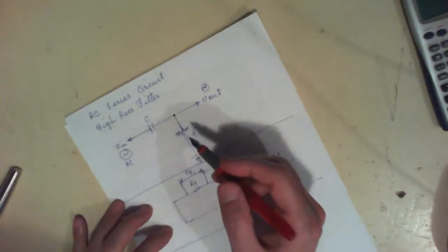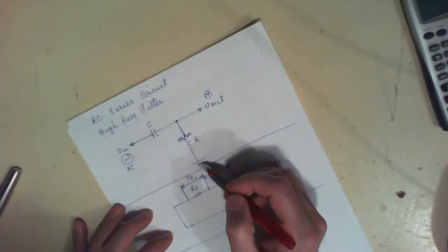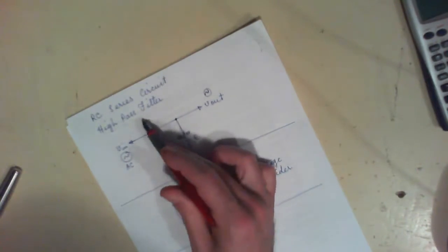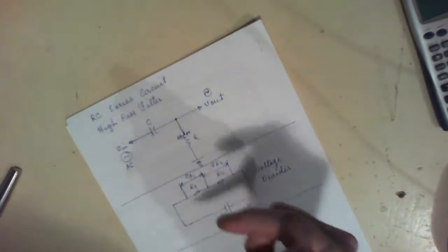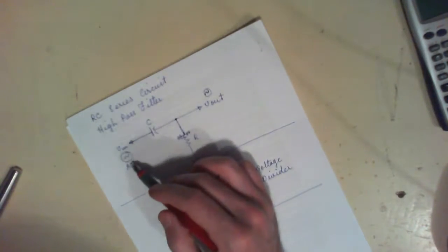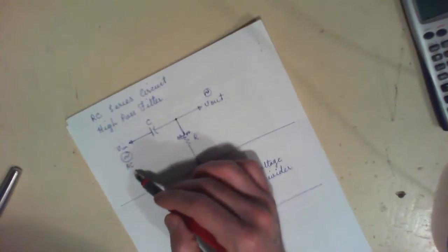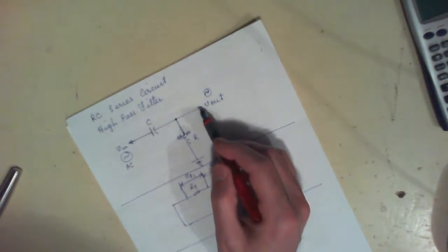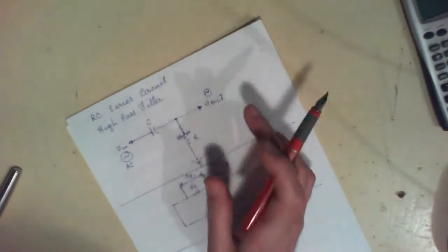What happens in this circuit is that you have your V of in here, and then this voltage goes to ground. Of course, there's a current that goes to ground, and there is some voltage drop across this capacitor and some voltage drop across this resistor. You have to choose the value of C, the value of R, and the input frequency in such a way that you have the voltage or the signal that you want at the output, and that's basically why it's called a filter.